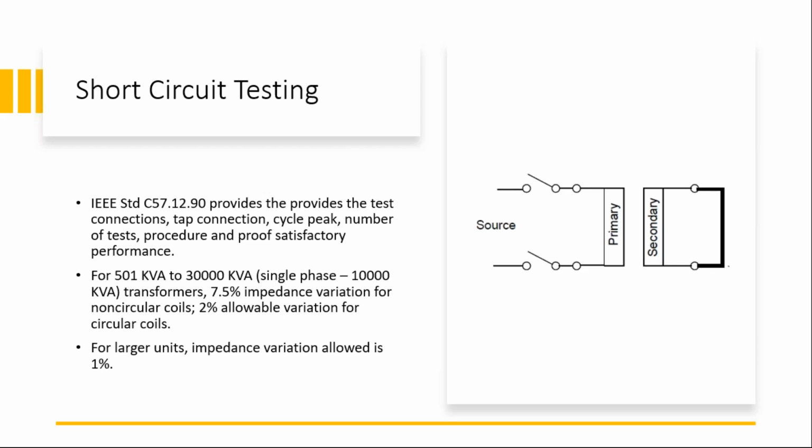Now coming to the testing, it requires very high power. None of the transformer manufacturers has this facility, and it is done in special labs. That's the reason I said it's very expensive. In the US, we have a KEMA lab in Pennsylvania, and there are some other labs in North America. But for bigger transformers, it has to go to Europe. Every transformer does not need it; in fact, it's not even one of the type tests.